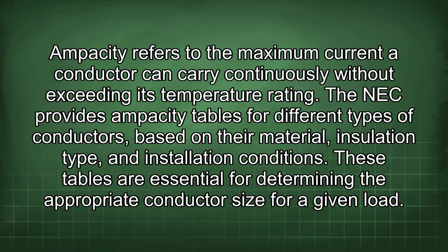Ampacity refers to the maximum current a conductor can carry continuously without exceeding its temperature rating. The NEC provides ampacity tables for different types of conductors based on their material, insulation type, and installation conditions. These tables are essential for determining the appropriate conductor size for a given load.